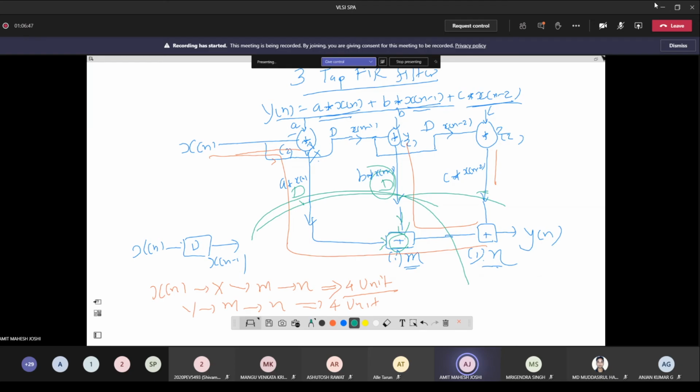But if I came early and you are not coming, or you came and I am not coming, then there is an issue. So over here, if this block is late by a 1 clock delay, where it provides the input to the adder, then this one is also late. It has to be late. Otherwise, if we count the previous value, then the functionality gets changed.